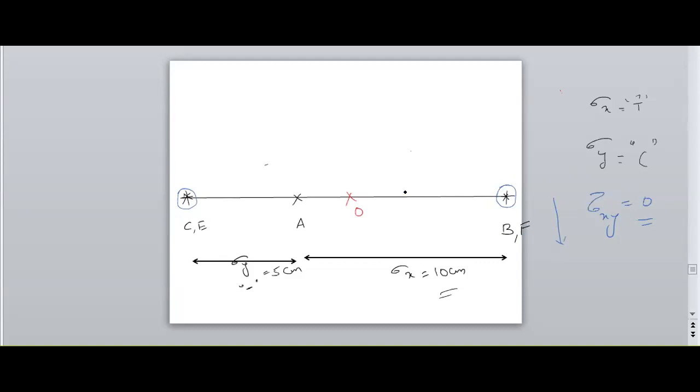Next, I need to join the perpendiculars and find the center of the point. That is the procedure. So I need to join E to F, and I need to find the O. Now E is on the horizontal plane and F is also on the horizontal plane.